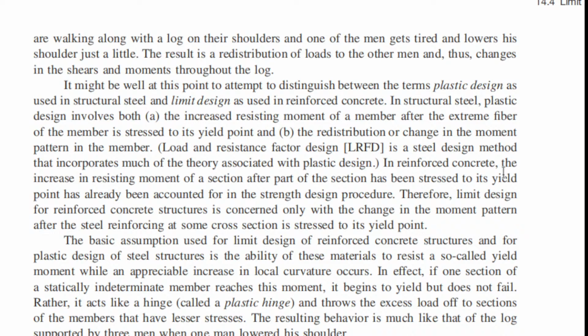However, in reinforced concrete, the increase in resisting moment of a section after part of the section has been stressed to its yield point has already been accounted for in the strength design procedure. Already accounted for. So there is no redistribution of load.